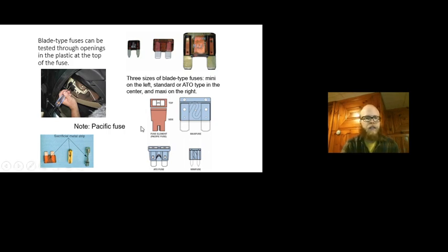Here we have a technician testing fuses to see if they're any good. On these blade style fuses, there are usually little test spots right on top where you can touch on each side and see if there's power on both sides. If my fuse were to break and become open because of an over temperature condition, then I would have power on one side but not on the other, because here's power coming in from the battery. There's an open, so I don't have connection to that same voltage on the other side. So we would just see the test light up on one side and not light up on the other.